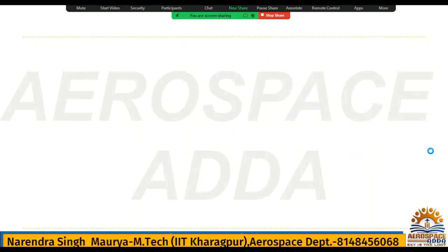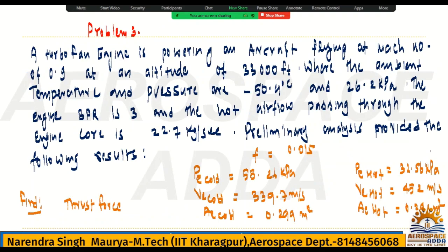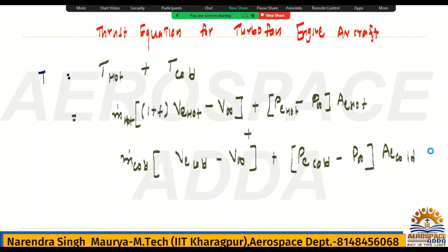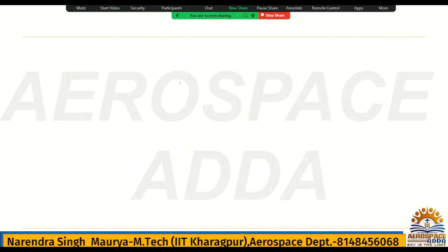Check all what we do not have. Mach number they have given to us. We do not have V infinity, na? Rest everything we have. Only V infinity is unknown. What is V infinity? It's the aircraft speed. How to get that? Mach number they have given, M infinity is equal to V infinity divided by root of gamma r T infinity, the speed of sound. What is the V infinity?